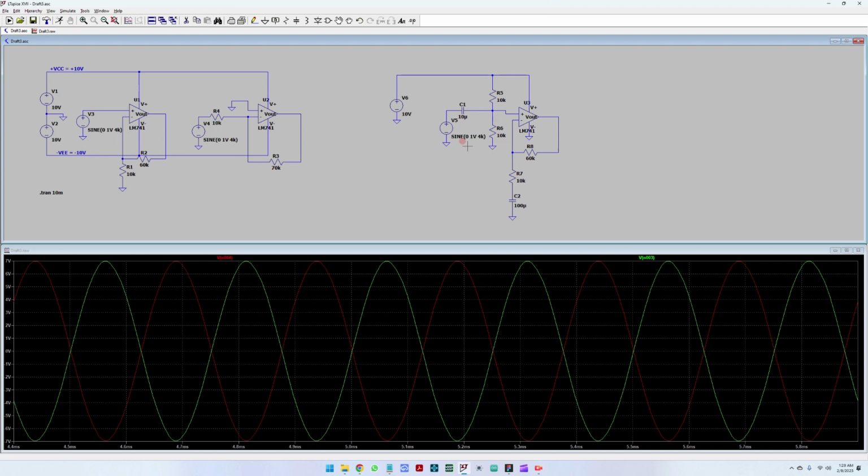Okay. And let's go in retrospect and look at the circuit. So we have a sine wave going through a 10 microfarad capacitor here, just to scale it between the inputs. We're taking the 1 volt peak to peak signal, and scaling it to 5 volts, or half of the power supply. Here we can change the power supply, you can make it whatever, of course not exceeding the maximum supply voltage for the component, but this value will vary with the power supply, and this means that you will always be centered in the middle of the value of the power supply here.